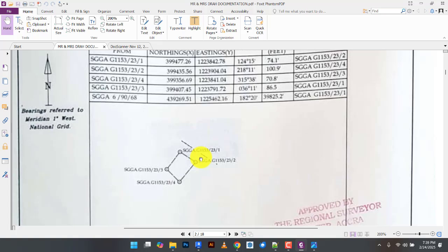It depends on the wind, the sunrise and the sunset. Very important. There's a functionality in Revit. We call it the solar analysis. So you can learn how to use it. After you put in what we are going to do, you can activate a solar analysis. You can put in a time, maybe 10 a.m., or 12. It will show you where the sun will be relative to the land, and it will cast a shadow so you can see how to position your building and all that.